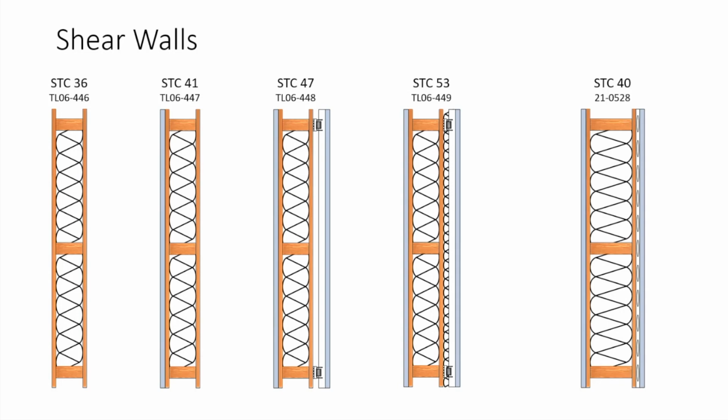But we've created this little bitty air cavity between the plywood and the drywall. And that air cavity allows some sound to build up. It's this little reverberant space, right? You've got these two hard surfaces that are constraining the sound in that space. So you'll get sound that builds up in there, and then you get more sound transmission because of that. Essentially, that's how it works. So if we put some insulation into that space, the insulation doesn't actually block the sound going from one side to the other, but it reduces the buildup of sound within that cavity, so there's less energy to go from one side to the other. So you can see adding the insulation gives us this big boost.